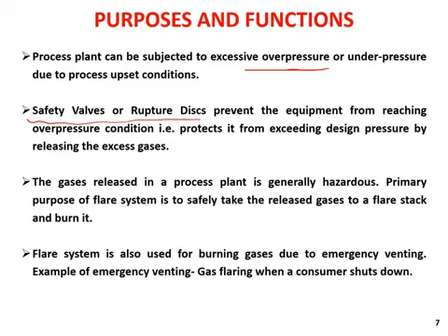Just let me clean this part. So when we have such a vessel, it can be a reactor, we can also design a safety valve or rupture disc. If the pressure in this vessel goes up, this valve takes action and will open and release the gas from the reactor. So those are the safety valves and rupture discs that prevent the equipment from reaching very high pressure.